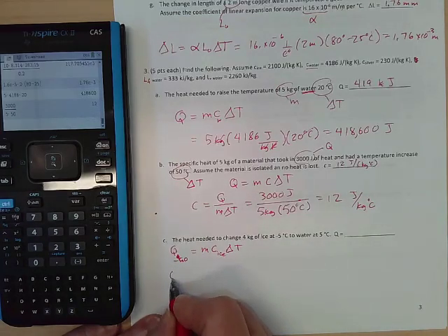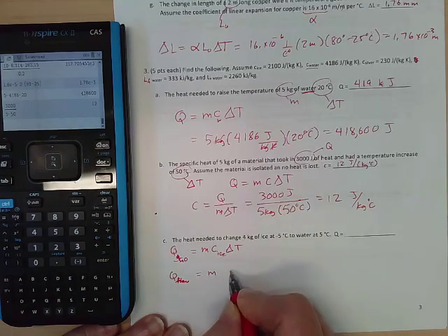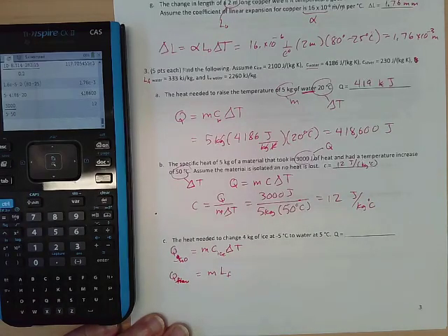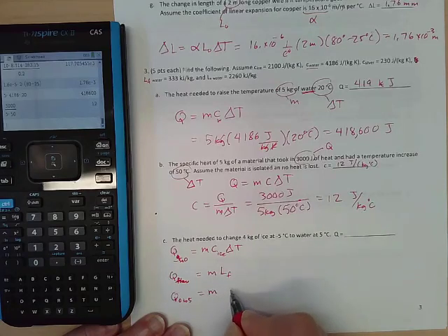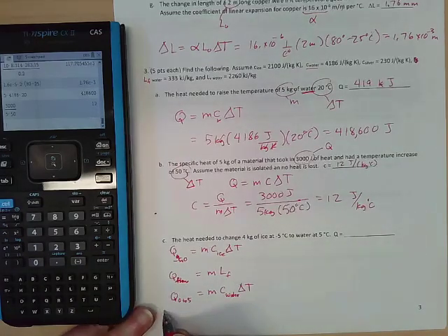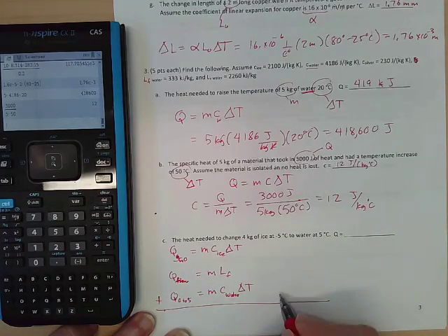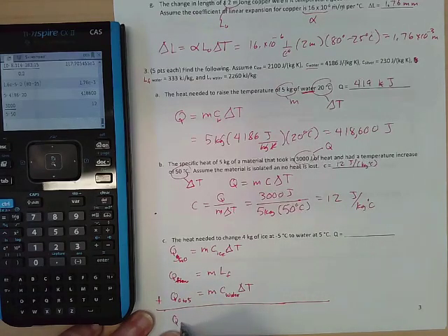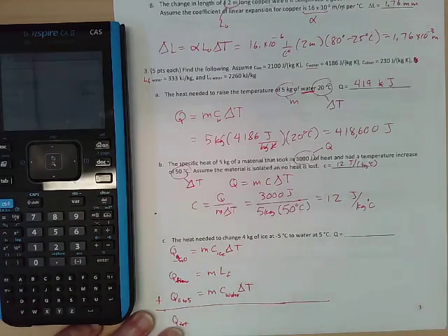All right, and then we're going to have Q to thaw. We're going the other way. To thaw is going to be the mass times the latent heat of fusion of water. Then that's not going to change the temperature. It's still going to be 0. Now it's just going to be water instead of ice. And then we want to go 0 to 5. Again, we're going to do mass times C, but this time it's C of water times its delta T. And so we're going to add all of these up to get our Q total, to go all the way from -5 to +5.